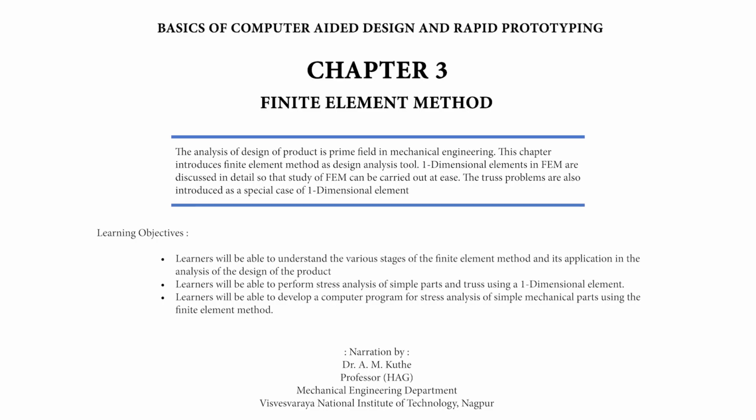The global matrix equation can be written using the global stiffness matrix. This matrix equation leads to 4 algebraic equations with 4 unknowns, that is Q2, Q3, Q4 and R, the reaction force at the node, that is F1. The above equation can be solved by applying the boundary condition. In the problem, the boundary condition is Q1 equals 0 as node 1 is fixed. This can be solved using the Gauss elimination method. Thus, displacement at nodal points can be found out.